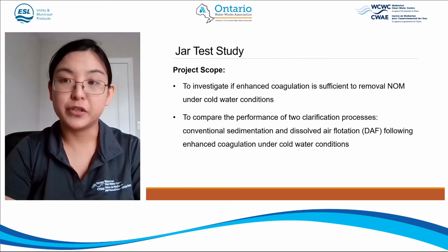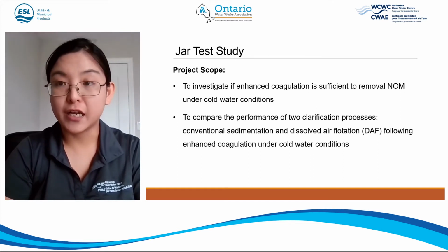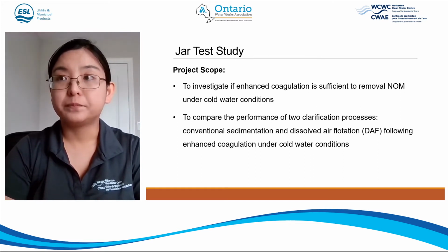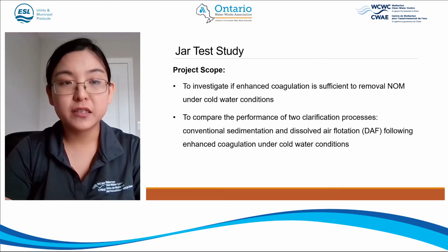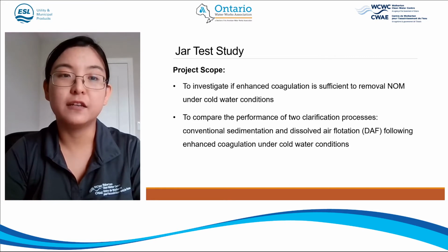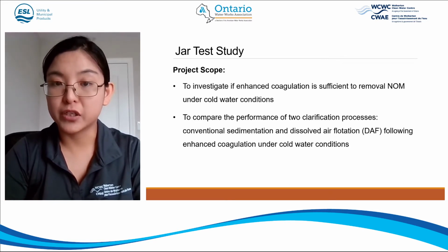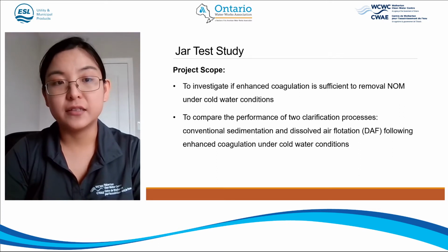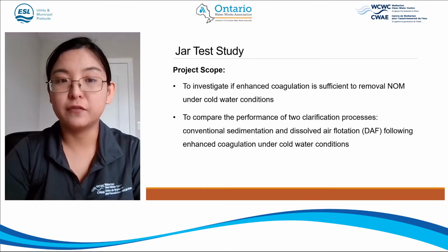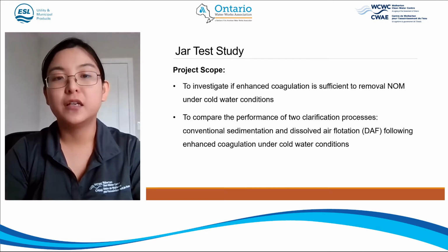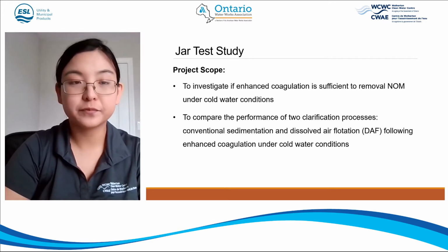So we had the community ship water to the center, and then we tested with 2 different jar test technologies and compared the 2 clarification processes. Our project scope was to investigate if enhanced coagulation is sufficient to remove NOM under cold water conditions. And the second is to compare the performance of 2 clarification processes, conventional sedimentation versus dissolved air flotation, or DAF, under cold water conditions.